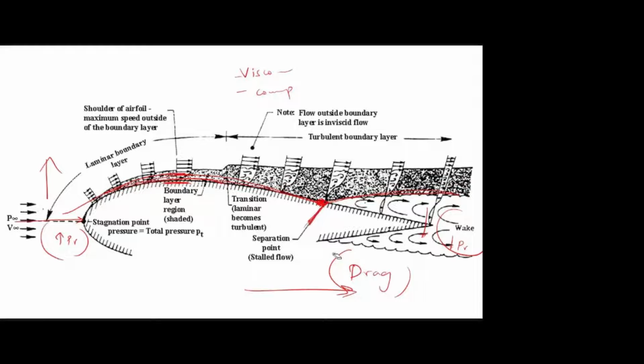Okay. We can say this is the pressure drag or form drag. Pressure drag or form drag, both are equal, two different names. And this flow separation, this wake region drag cannot be avoided. It will be there in the physical flow. The only possibility is we can delay the flow separation.